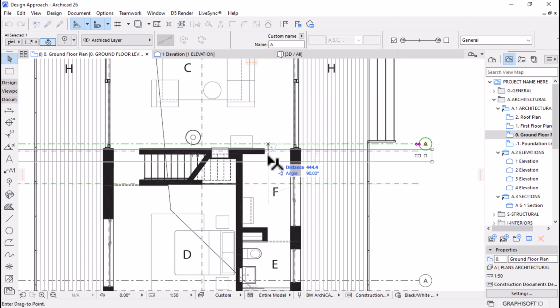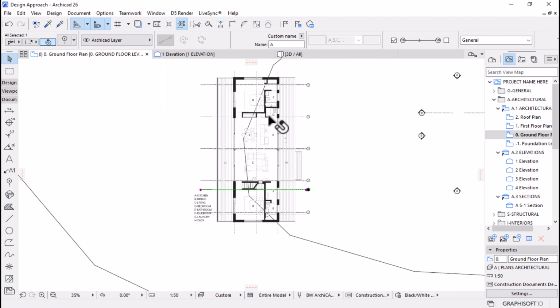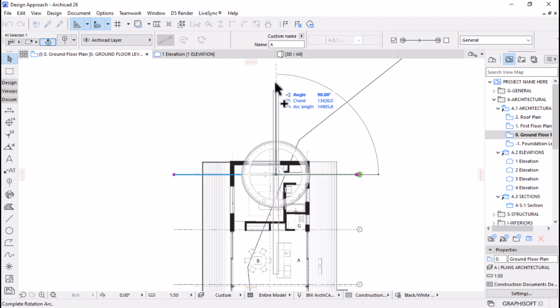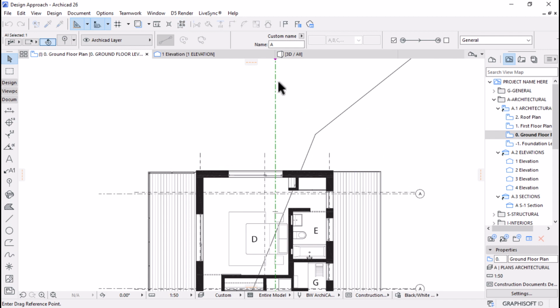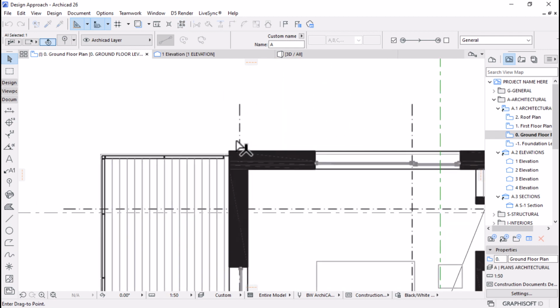Let's try the copy, make it 1.5. Okay, let's go for vertical grids. I can rotate a copy by Control Shift E on your keyboard. Let's rotate a copy of this grid like that, then move it to the place for this wall.